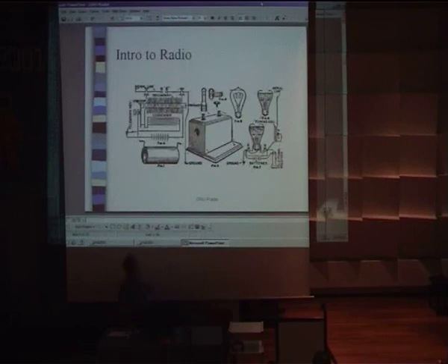This is a 1910 vintage spark gap transmitter and receiver. We've got the transmitter here on the left, and the receivers are the two light bulbs, where you knock the tops off the light bulbs and fill them with water; those are two crucial pieces of the receiver. We would call these wideband jammers right now, literally prohibited. There's zero tuning on the transmitter. You basically get whatever the frequency of that spark is, and if you look at the spectral distribution, it gets really broad. But anyway, you can just hook this up and turn it on, bothering all of your neighbors.